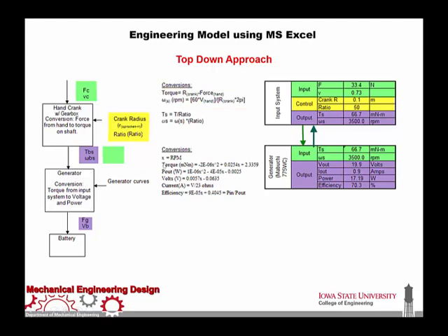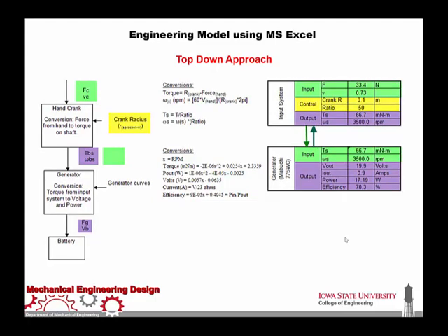So looking at our modeling system, we have our equations here for the generator, and those will give us our outputs here in the Excel model if we insert these equations into these cells in the Excel model. These models can also be done using EES or MATLAB or MathCAD. Any of these analysis softwares work well, or they can be done simply with an engineering problem paper and writing out the equations longhand and solving them on a calculator. Important thing is document your analysis so others can understand how you came up with the results that you have.